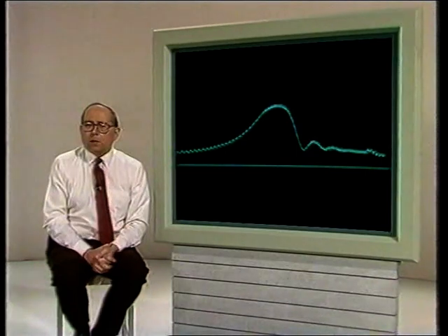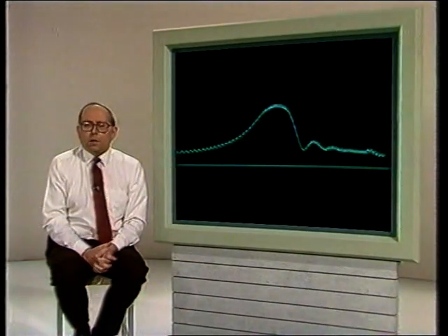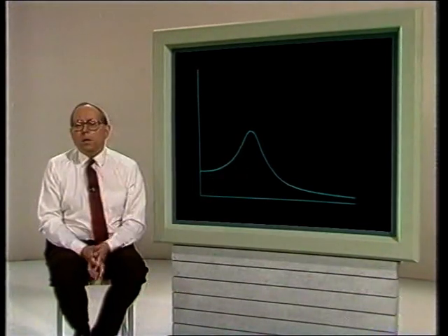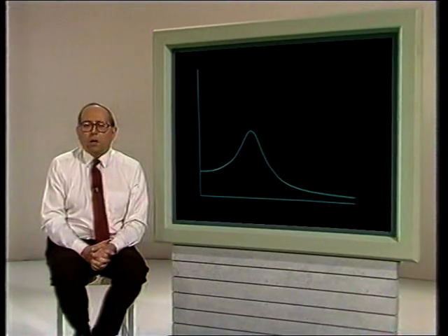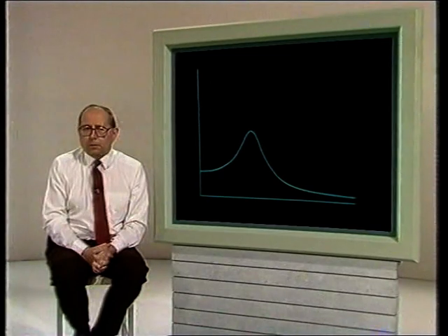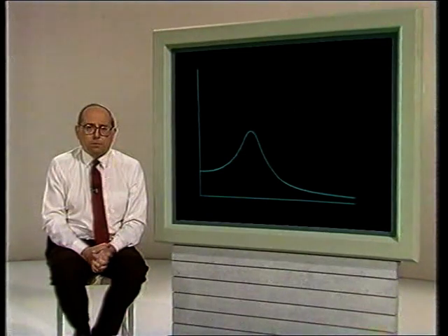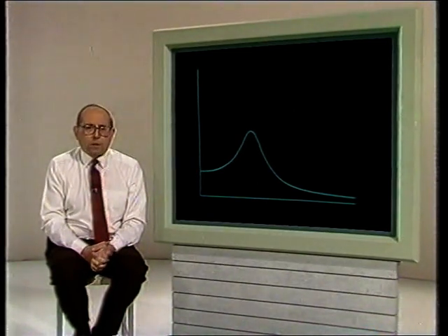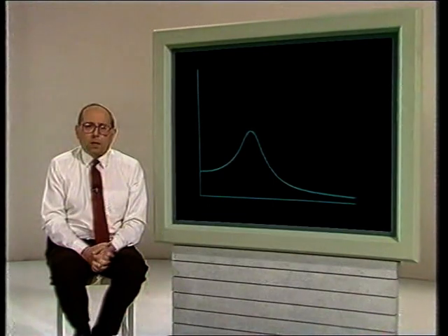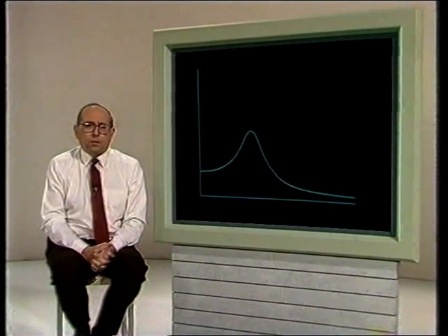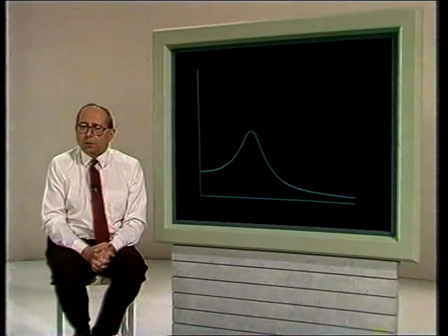You may have noticed that this transmissibility curve doesn't have quite the same smooth form as the ones shown in the unit. This one, for example. The difference happens because the measured curve was plotted from measurements made while the frequency is increasing. It includes a transient effect. The theoretical curve is calculated for a series of constant frequency values. In practice, the more slowly the frequency is increased while the response is measured, the closer the measured transmissibility curve will be to the theoretical form. Knowing the transmissibility results, we're in a better position to make design adjustments to avoid resonance.